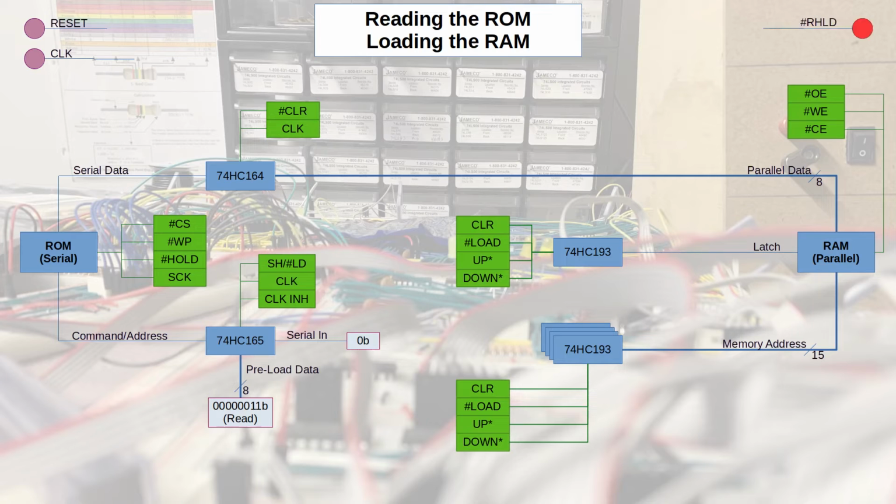an input. The output of the circuit is going to be a reset hold signal, meaning that it is still in the process of resetting and copying that data from the Serial EEPROM onto the RAM. This one is going to be an active low signal because the ICs that I'm going to use to drive that are going to be an open drain in CMOS, meaning that the 2 states are either low or it's high impedance.